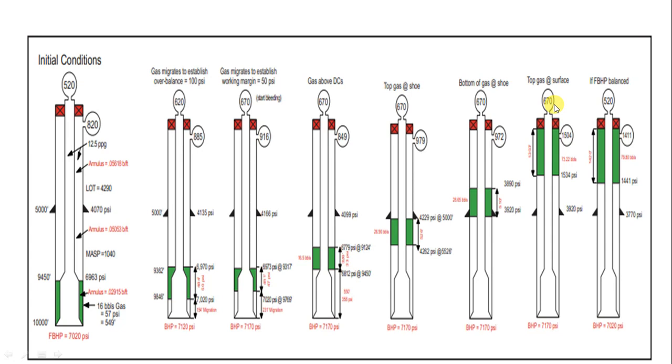Once you finish bleeding the pressure and keeping the casing pressure so that the bottom hole pressure is overbalanced by 100 psi, at this time you can fill the kill mud by using the kill line. And at this time it's called lubricate and bleed.